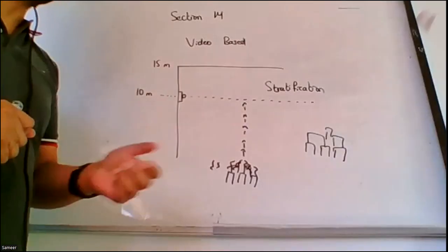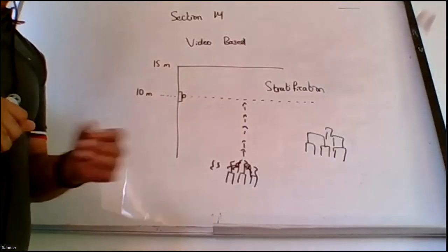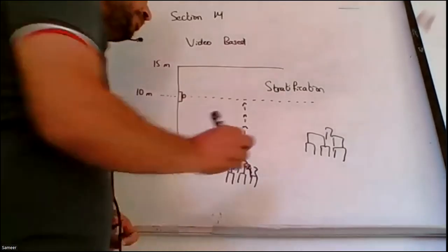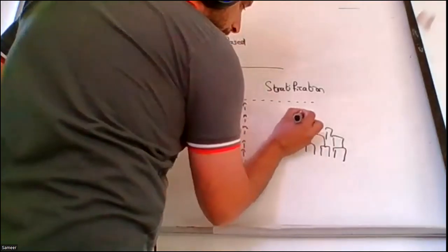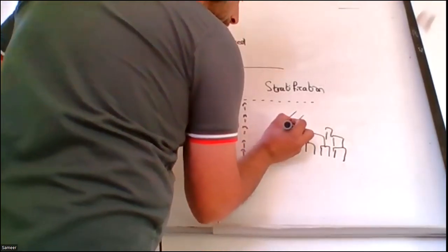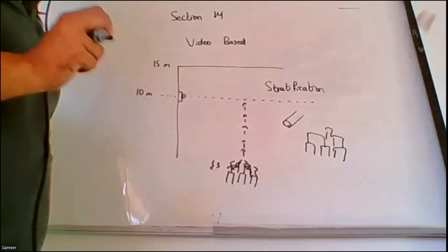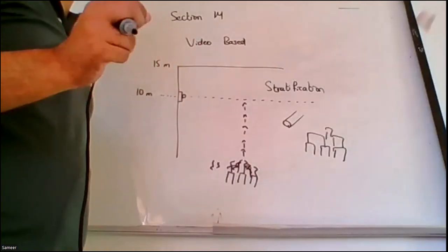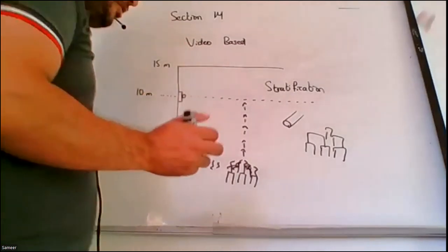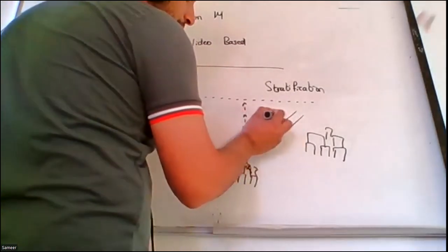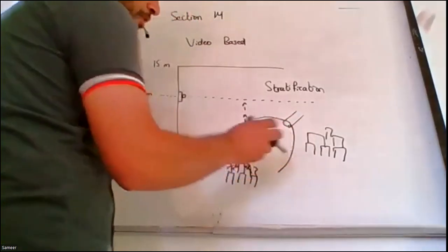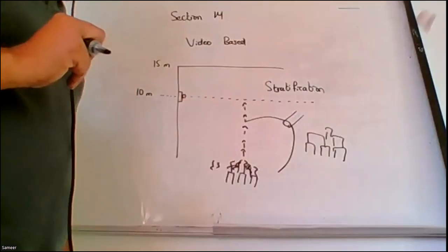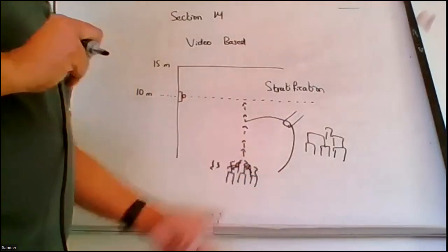For that purpose, what we want is a type of detection that can actually give me an alarm at a very initial stage. For that purpose, I use video-based detection. But remember, video-based detection is expensive, so we cannot protect all warehouses with it. It also requires large maintenance. Now what happens in video-based detection? It has a conical view of the area, not the whole area, but a conical view of the surveillance of the area that it can cover where my combustibles are available.